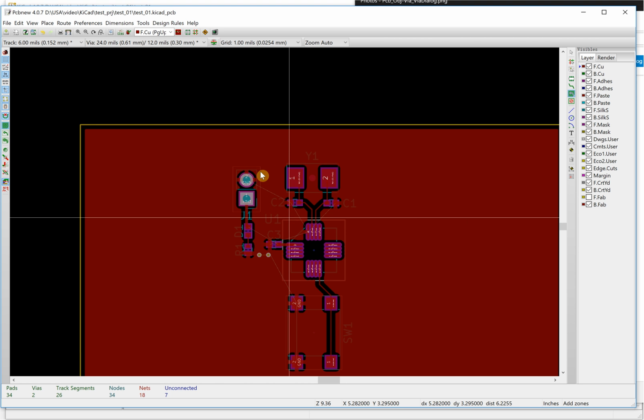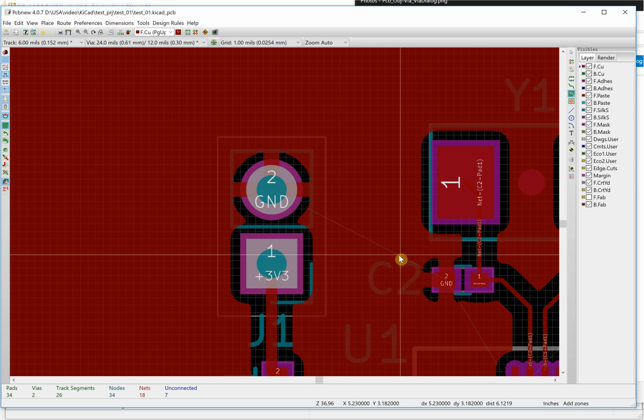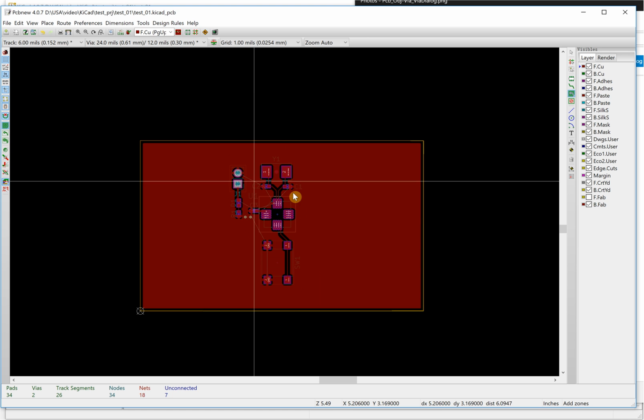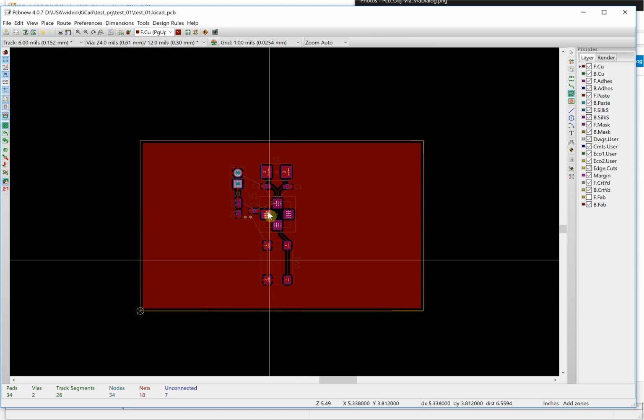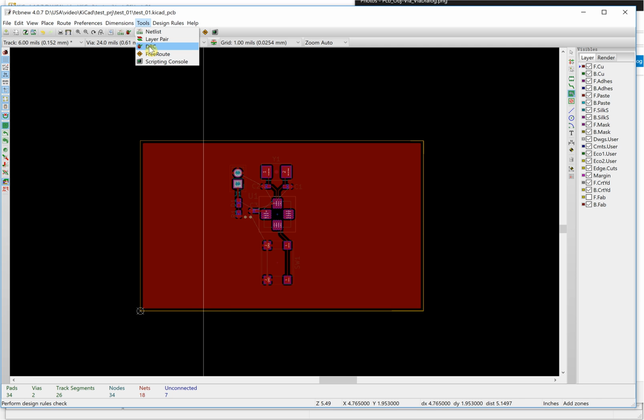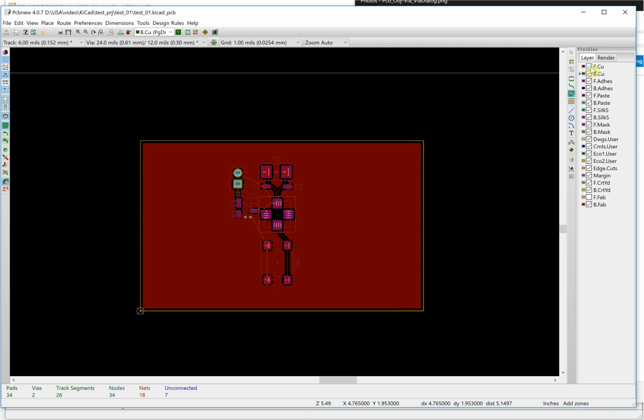Okay, you will see there is still some white ratsnest here that didn't connect together, and here didn't connect together. It means some nets are disconnected. You can choose the DRC to check whether your board is correct or not. But before we do this, we add another layer. So this is the bottom layer, and we fill the copper on the bottom layer too.